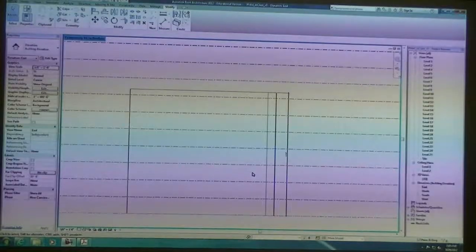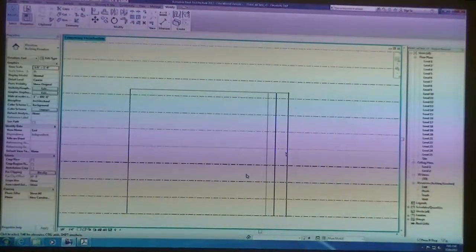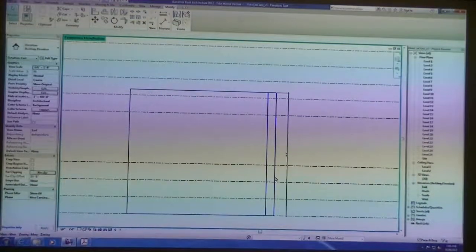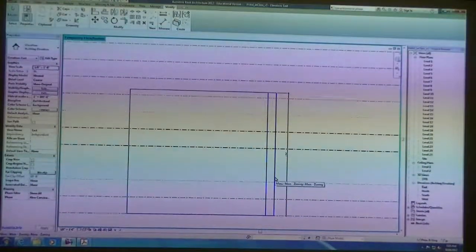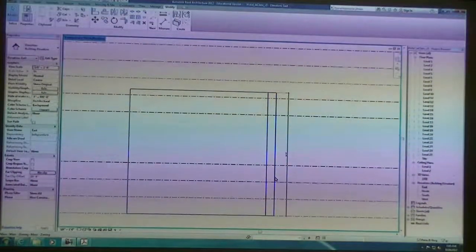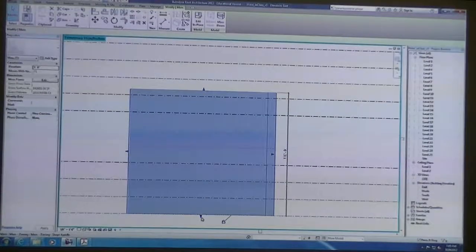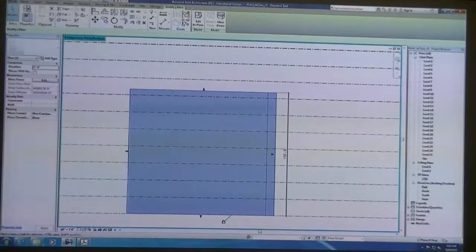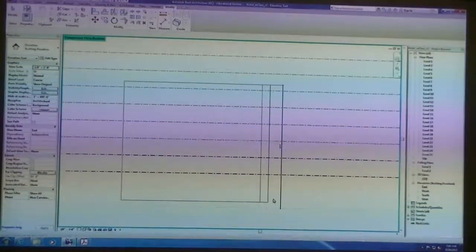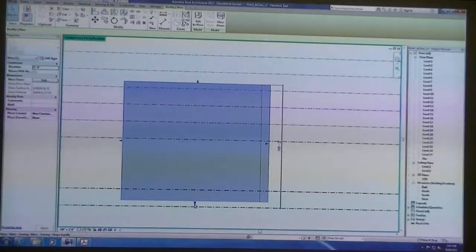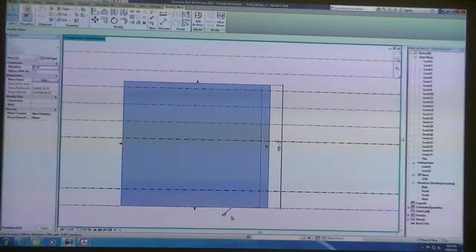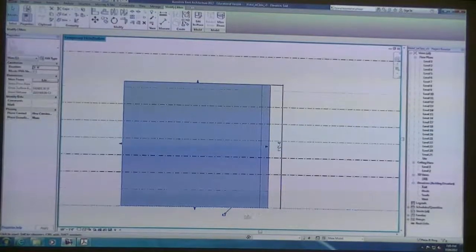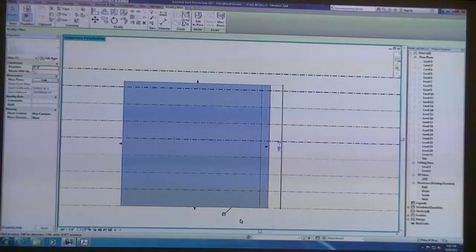How did you get it to go straight back down without moving? Is there a way to go back down? All I did was select the mass, and you get these drag handles, and you can just drag this up and down. Oh, you locked the dimension and then did that. Yeah, I had my mass floating up here, and then I dragged that handle down, and when you snap to that lower datum line, that's when I hit the lock button, just so it doesn't float up again.